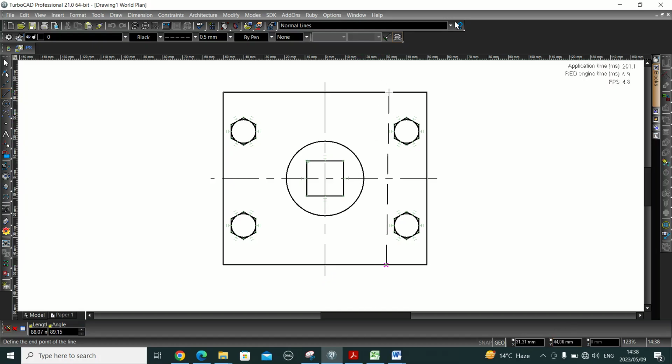There is our line. Press now shift on your keyboard. But make sure that this snap is highlighted. Mine was gray, so I need to turn it on. You can see what it does. It makes sure that your line will end exactly on this line. Now press the shift button and click. That one is in place.